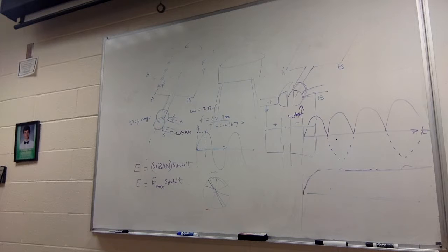Now that is an adapter. I'll talk about this later also. Now what goes in here is 110 volts AC, right? But what comes out from here behind is DC, positive, negative. Now how is that DC going to be similar to that is if you use a capacitor to smooth it out.